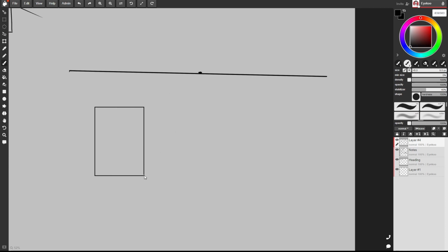Now, like we did before, I'm going to connect our corners to the vanishing point. And then our horizontal lines and our vertical lines, because they're not moving away from us, and we're seeing this plane perfectly flat facing us, they're going to remain perfectly horizontal and vertical all the way through to the vanishing point. So I can drop a vertical here, do a horizontal line there, and we have our box.